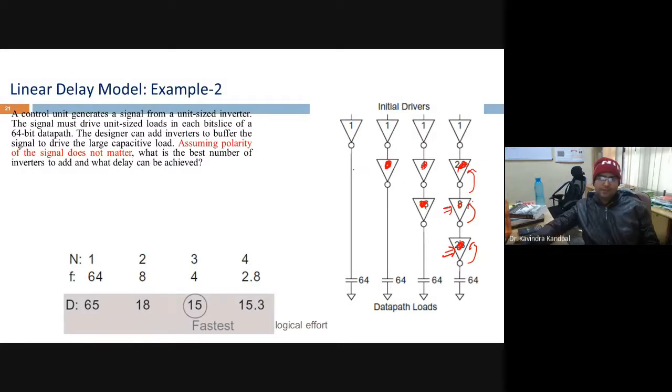The very simple thing is that you need to get what is the F. Very first thing, you need to find out F, which happens to be not only logical effort but also electrical effort. B into H, I would always call both of them together as electrical effort. Once you have found F, now the question is, you are not very sure whether you need to drive one through one, because right now you are doing a kind of hit and trial process, right?